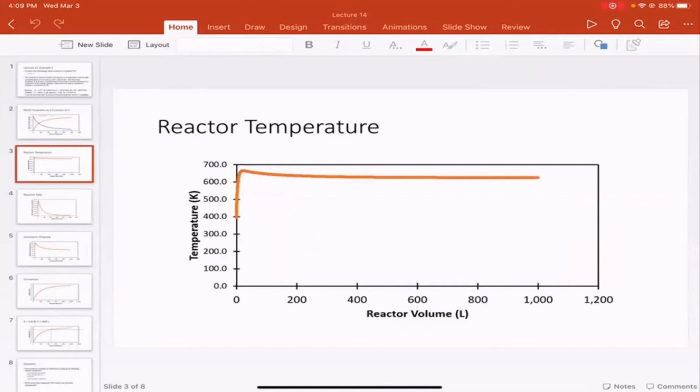And then what happens is that as the reaction rate decreases, you start consuming species, for example, the reaction rate comes down, and then the jacket is able to remove heat faster than it's being generated. So the temperature here actually dips a little bit, and eventually over the reactor length, you get to simply the jacket temperature. And it's as soon as the heat transfer rate can keep up with or exceed the reaction rate here.